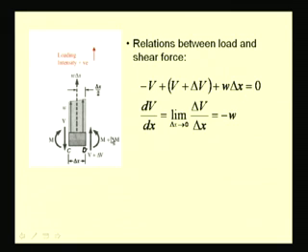In the limit, we get dV by dx as minus W. So, if we integrate this quantity, we get the shear force for any particular section between CD.